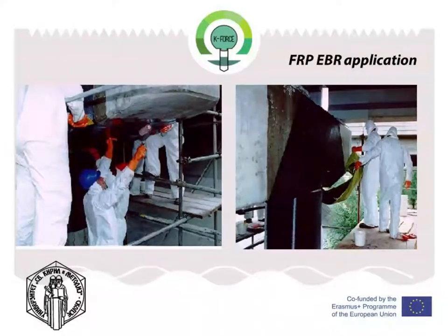To achieve the required evenness of the concrete surface, it is specified to apply a primer. This shall be done in accordance with the specification given by the manufacturer. A low viscosity resin is applied to the concrete with sufficient thickness by means of a roller brush. This process is known as undercoating.